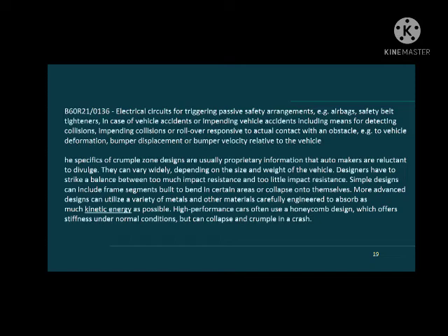When the forces from the occupant acting upon the seat backrest exceed a particular level, the WHIPS system is activated. Hence, no external sensor system is required to activate it. The aim of the primary phase is to let the occupant sink into the seat, thereby reducing the space between the torso and the headrest.